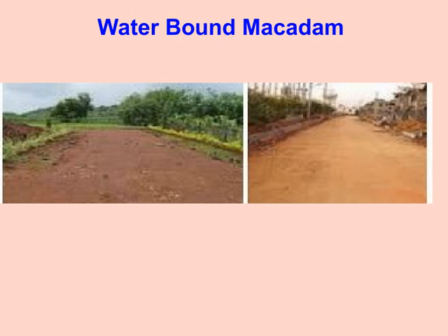One of the key points here is the importance of proper water content during the compaction process. Too much water can weaken the structure, while too little may prevent the stones from binding effectively. So, achieving the right moisture content is critical for durability.